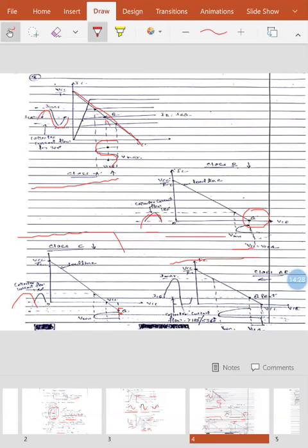So we are going to get only a very short duration of the cycle at the output. And when you go for class AB, it is nothing but a transition from class B to class A. Here we are not going to get exactly half a cycle, but a little bit beyond that, and not a complete cycle.